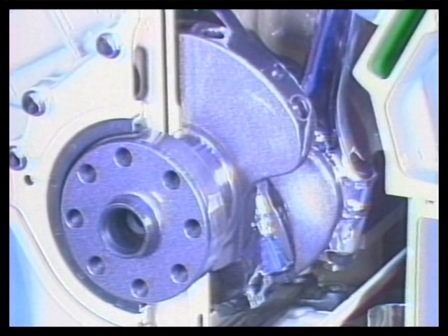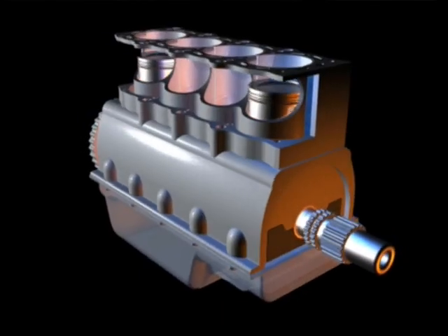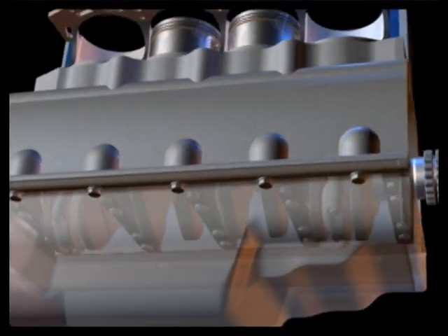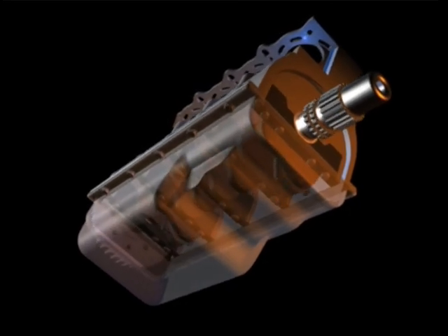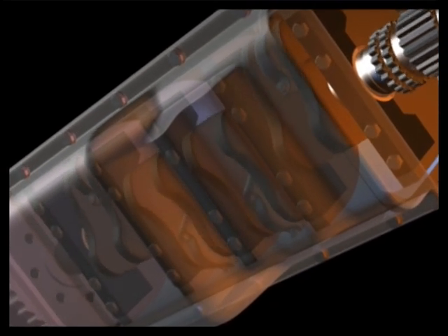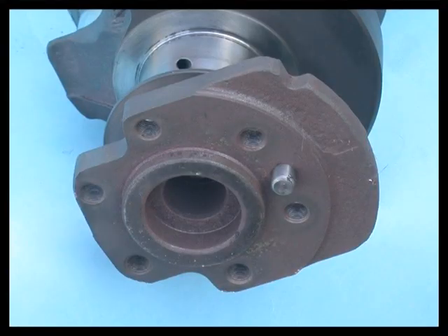As this engine cutaway shows, the crankshaft mounts in the lower area of the block. The crankshaft mounts on main bearings, similar to the rod bearings. The main journal of the crank rides on the main bearings. This allows the crankshaft to spin freely. The main journal of the crank remains stationary, while the rod journal rotates around with the connecting rod. The crankshaft transfers power to the transmission and the drivetrain. A flange on the rear of the crankshaft fastens to the clutch or transmission.